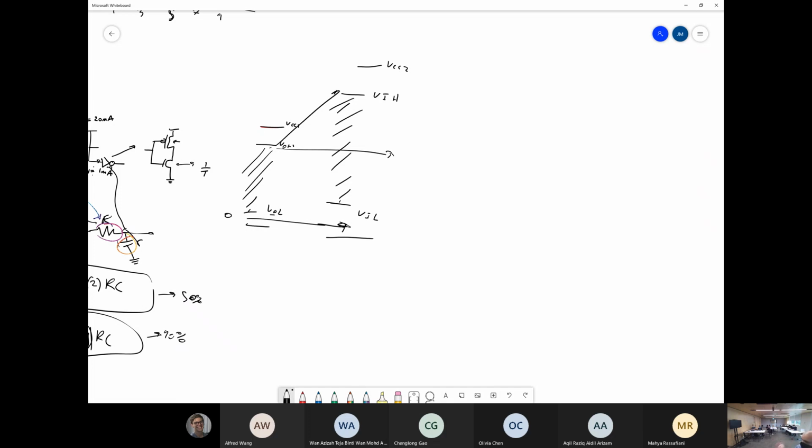So the most basic way of doing it is to use, well, what do we need to do to the signal? Do we need to attenuate, make it smaller, or amplify, make it larger? Go bump it up so it's there. Which is? Amplifier. Yep, cool. So we need some sort of an amplifier. The most basic amplifier we can make is, if you remember from 2133, a common emitter.